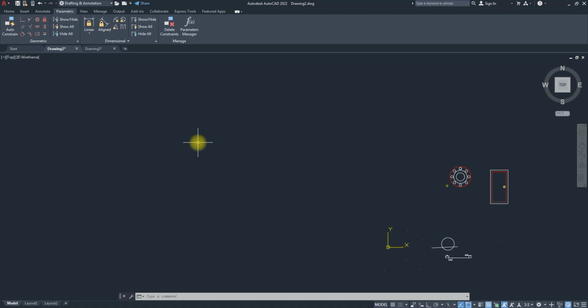And we have two types of parametric constraints. We have geometrical constraint and we have dimensional. So geometrical is talking about the geometric relationship between them. So example of the geometric relationship might be that tangent we looked at. When we are trying to create line, I wanted that line to be tangential to the circle. That tangent is a geometrical constraint between the circle and the line. We have concentricity relationship, we have collinear, so on and so forth.